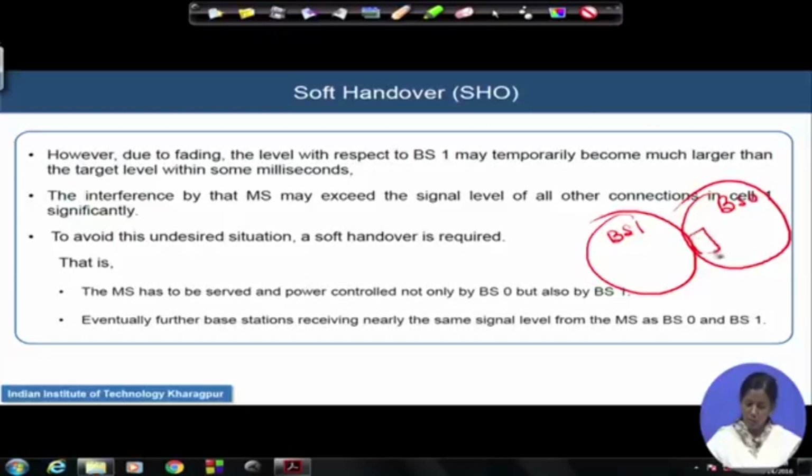The mobile station is close to the boundary of cell 0 and was transmitting via the power control mechanism, enrolled to base station 0, because it measured the received power level from both base stations and found it higher from base station 0.